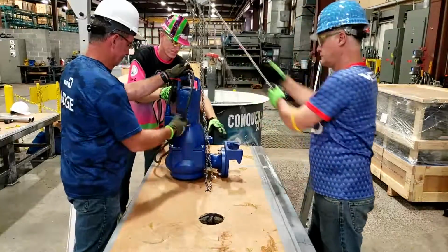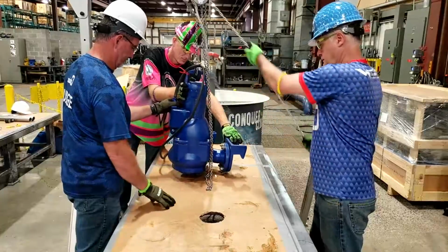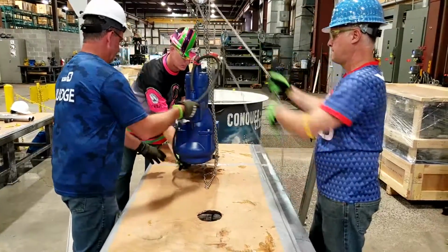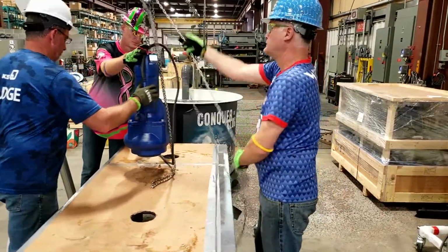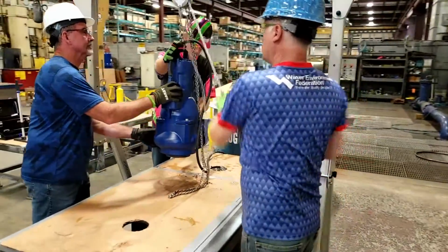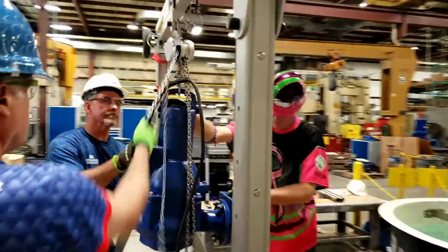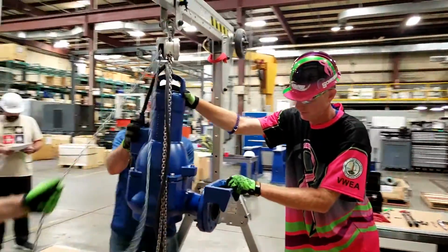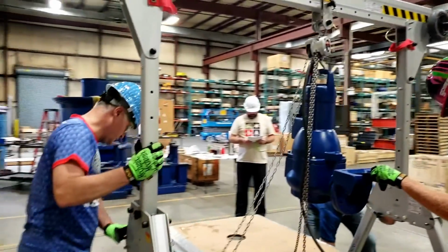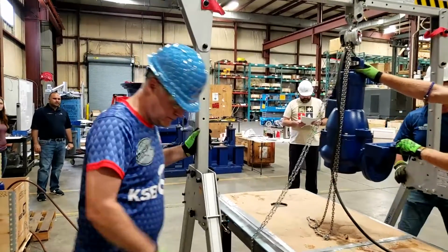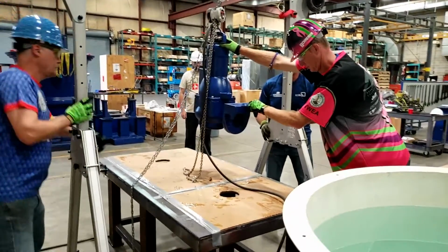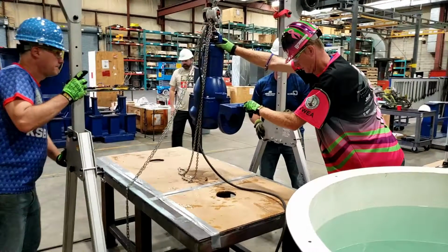Once the wheels are locked, connect the pump to the hoist. Using the hoist, raise the pump to the desired level. Once the pump is raised to the desired level, you may unlock the wheels. Note, at no time can the pump be raised or lowered using the hoist with the wheels unlocked.